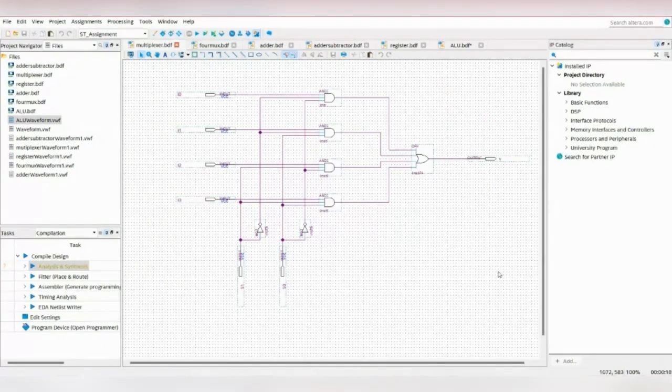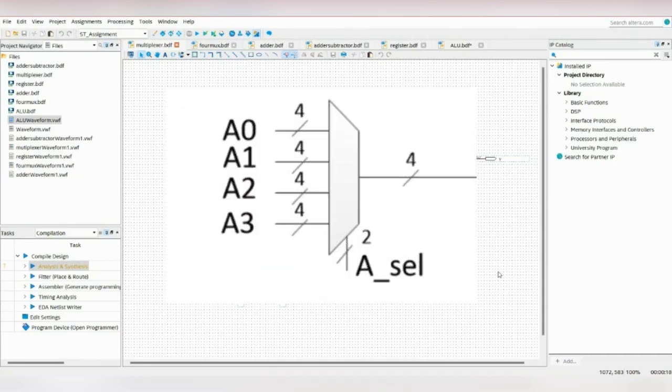After the gates are connected, we need to run the circuit. If it doesn't have any problem, we will press File and press Create or Update. Then we press Create Symbol Files for Current File to create the 4-1 multiplexer gates and save it.